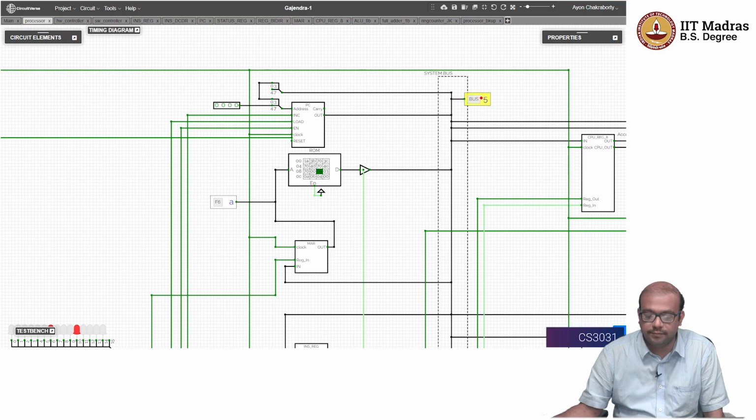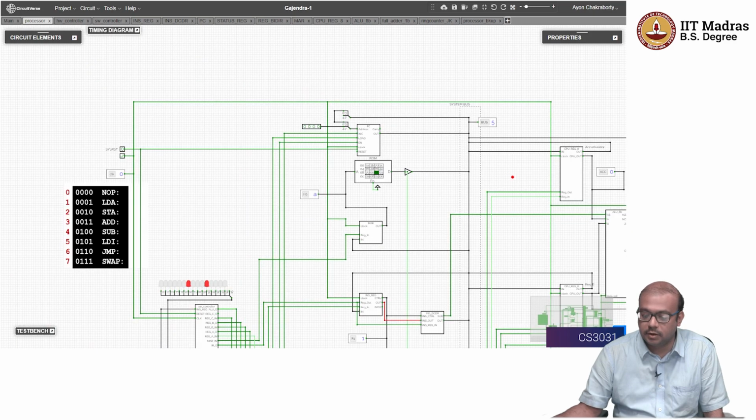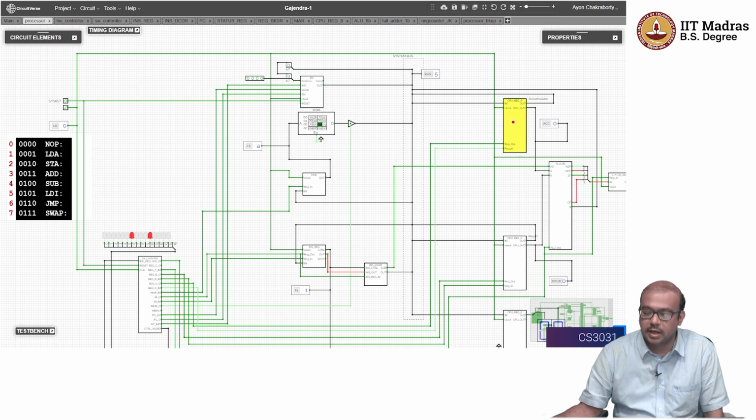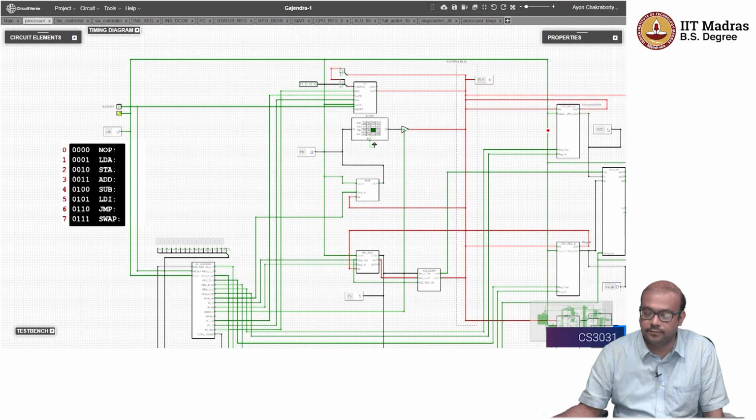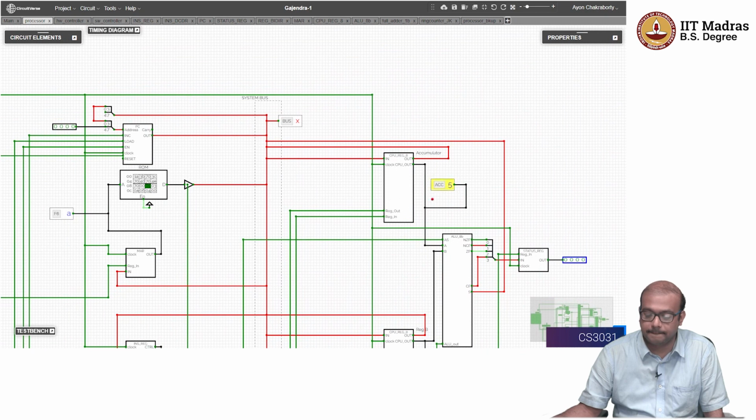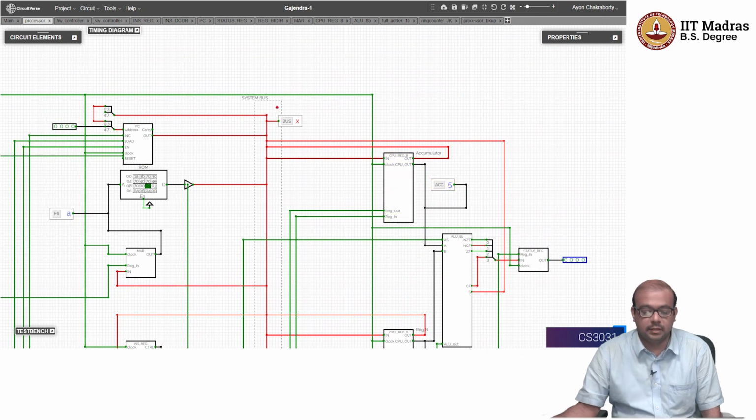so the bus contains the value 5 and the accumulator should also contain the value 5. You cannot see the content of the accumulator directly, only whenever there is an output you can see that. So I can put one more clock pulse. Now you can see 5 is there in the accumulator. All the lines have become red because at this point of time nobody else is writing any control signal. So all the control signals are now revoked, all the control signals have become 0.